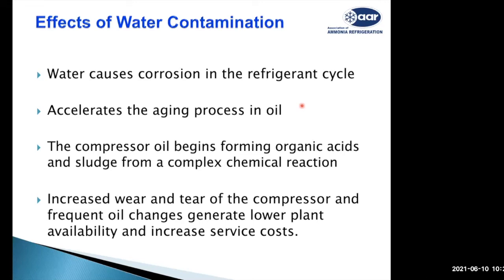Also, the oil starts forming organic acids, because those are natural oils, and they may generate some organic acids. That will create sludge formation, and then that will start damaging the compressors. Because of the failure in the compressor, there will be oil failures that will lead to more wear and tear of the compressor.